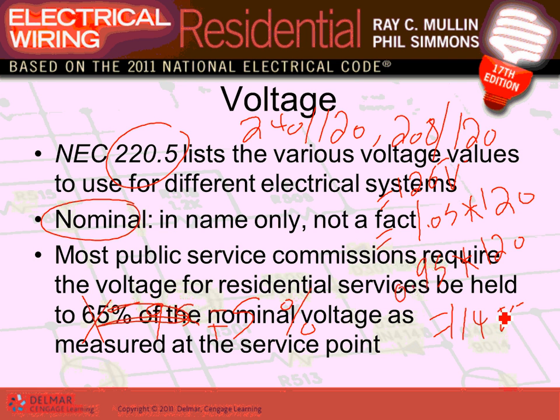The okay window, that's the most confusing thing, because they think, especially you guys, who are not going to be carrying tools, but there will be a project manager walking in and saying, oh, damn it, there's no 120. Equipment are rated for a window. 120 is just a nominal voltage.